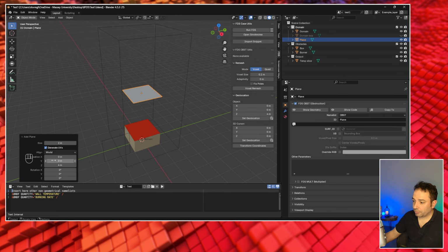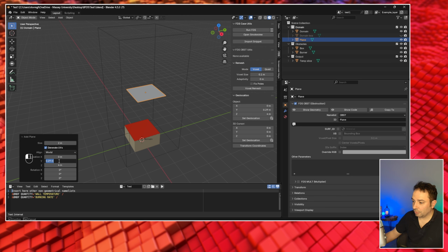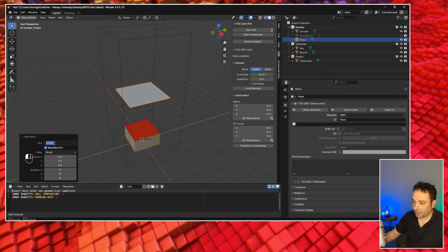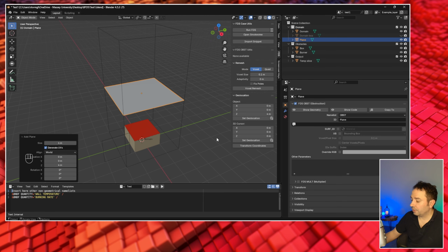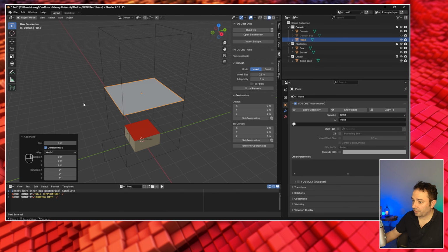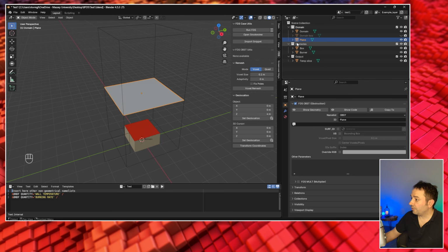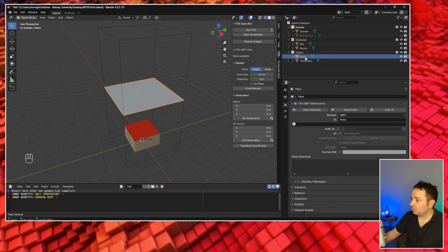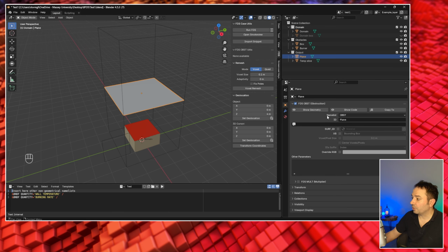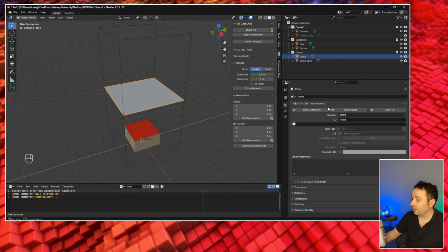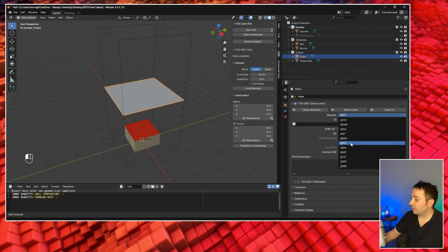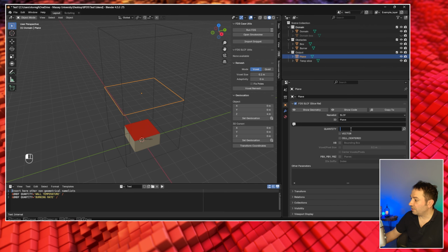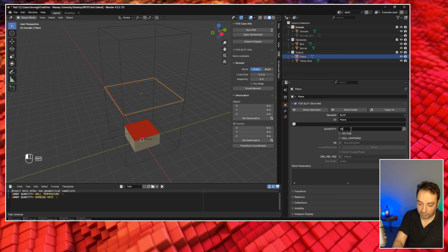And the other option that we have here, of course, is to locate it in a different area. The sides, I'm going to expand it to 4 so you can cover the full domain, and press anywhere here in the domain. So you can see the new plane, it's there. What we need to do is to move it here in the outputs, but the really important thing to do is to go here in the FDS characteristic of the object and select slice. So you can see that now it has disappeared, and here we can type velocity.